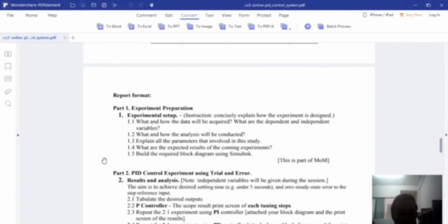The parameters that we got from this method will give us a response with an overshoot but with a good settling time. Secondly, for the P controller using the PID tuner, we replace the gain block we used previously in the Ziegler-Nichols method with a PID controller. Then, the parameter involved in this study is the PID structure for Simulink, Kp plus Ki/s plus Kd·s.